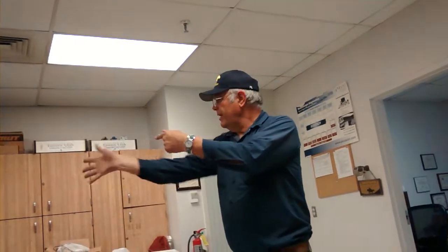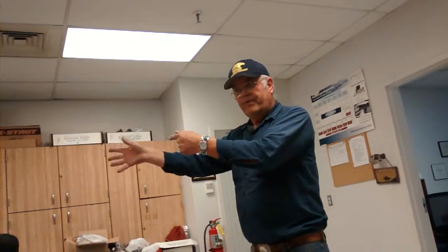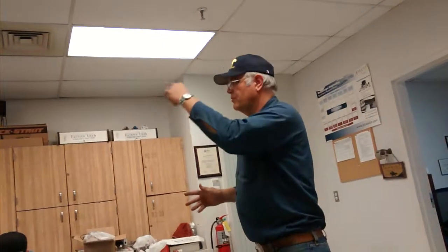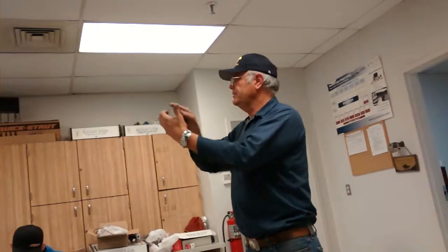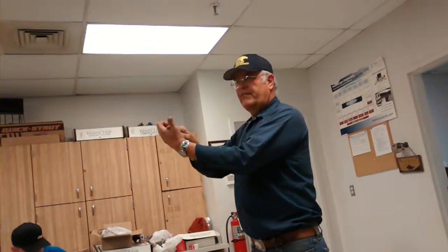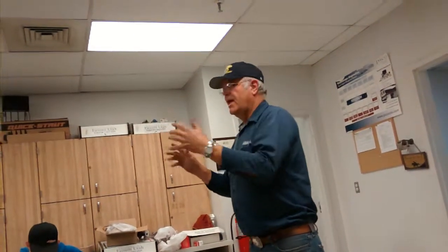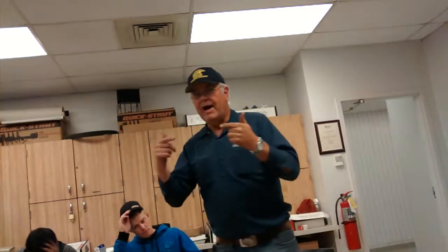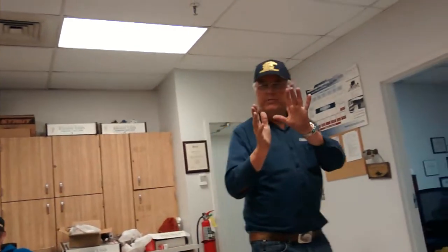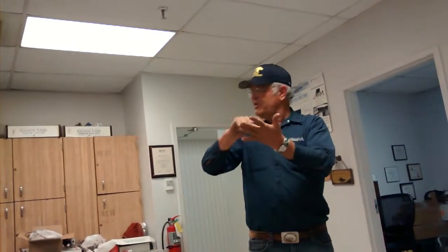The computer may break it out in 40, 50, 60 different wires, but each one of those wires is a series circuit fed by one source, which makes it series parallel. One feed side by side. If you make it too complex, you will not figure this stuff out. If you keep that in mind, and you find which part of the circuit that I'm checking, which one of those 65 wires has a problem.